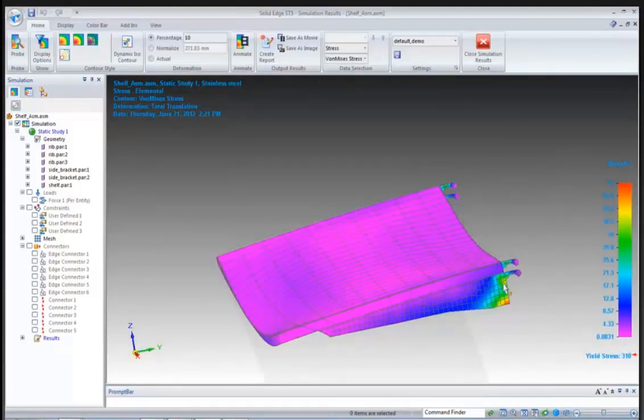And because stress is equal to the force over the area, when I make the area extremely small by making it an edge or a point, the stress gets infinitesimally high. I mean, it gets extremely high, and we call that a singularity. And we know, because you can see it here, there's high stress around where I applied those constraints. And we know that this is not our area of concern, so we're not going to look at that. This is our area of concern. The principle says that the stress and the displacement in this area will be valid, we just can't look at it in this area. I hope that makes sense.